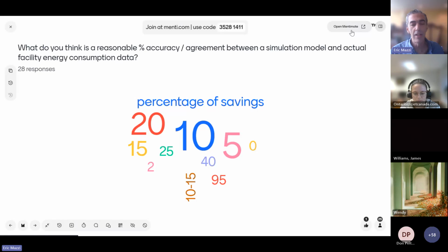of the project? Who's the lead M&V professional? What are the results of the M&V going to be used for? Probably some financial transaction, and all those factors, it gets to be a judgment call. In general for industrial, I found that 5% works. I've cited another M&V standard called FEMP, the Federal Energy Management Program in the US. It's usually used for buildings, not industrial, but it does provide some guidance on what agreement there should be between model and data.